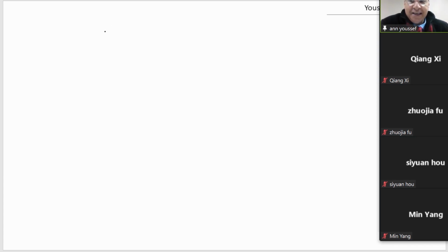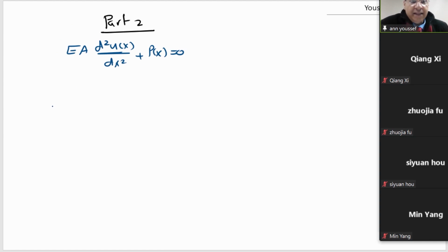Reviewing part 2: in lecture 1, we solved our main problem, EA times d²u of x by dx² plus p of x equal to 0, using direct integration. And in the first part of this lecture, we solved it using superposition.